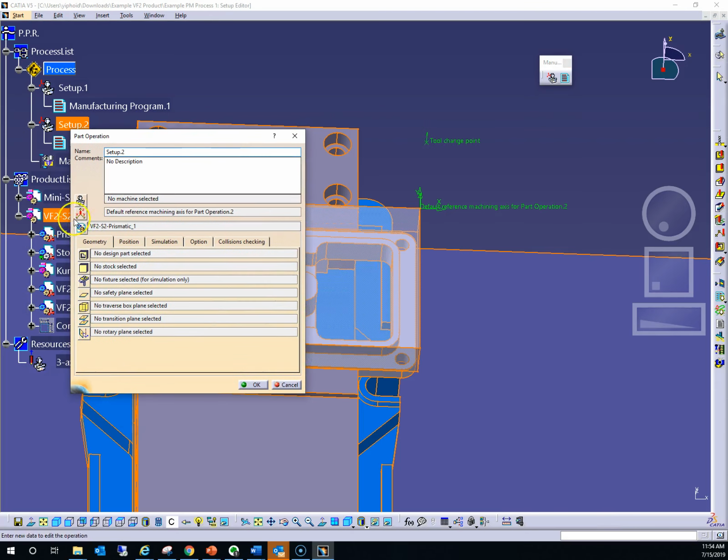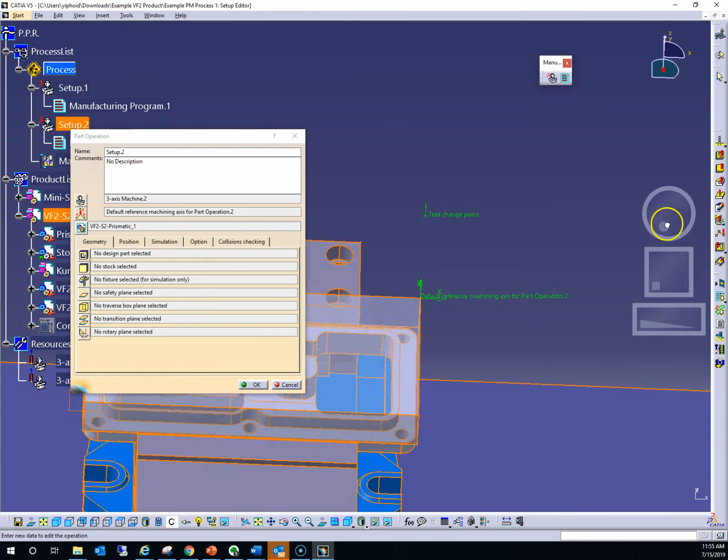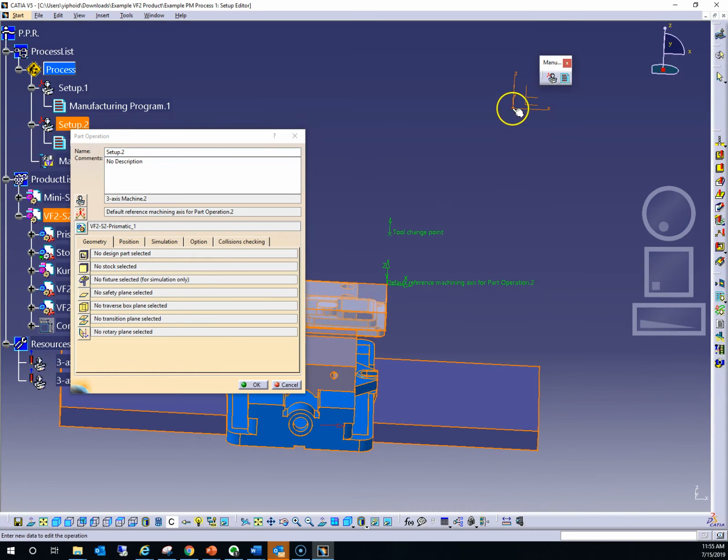We're going to go to our machine. And again, our home position is slightly different from the coordinates for the first setup. So I have them recorded here. I'll just type them in: 8.844. The Y shift is 4.401. And then the Z position is 12.658. So again, that establishes our home position at this coordinate system up here with respect to our machining coordinate system.